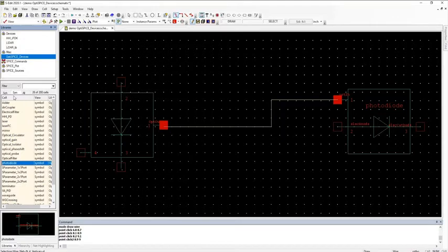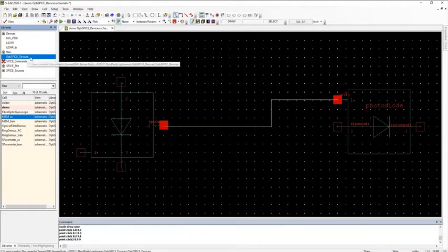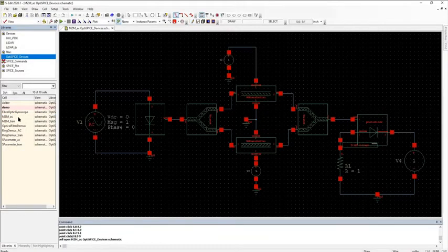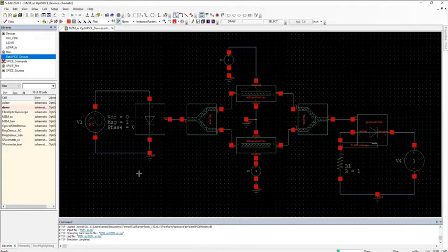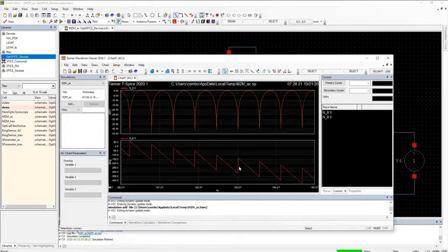These examples on the left that you see come pre-installed with our model library, OptiSPICE devices. And as I said, you can do frequency and time domain analysis. So this circuit is set up as a Mach-Zehnder modulator. We can do the frequency analysis on it by clicking Start Simulation. Once you hit simulation, a netlist is created, and then T-Spice is called alongside OptiSPICE so that we can run optical and electrical simulations. So this is, as you can see, the frequency domain solution for the Mach-Zehnder modulator.